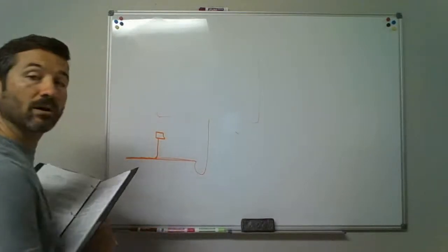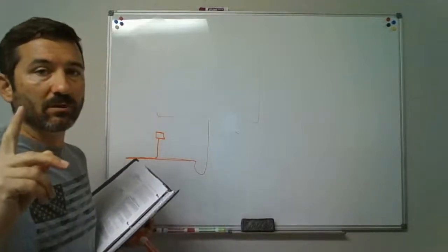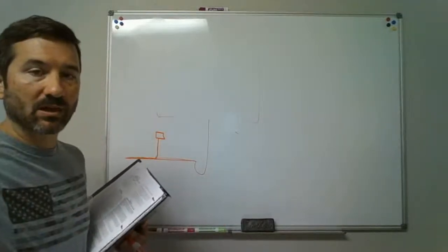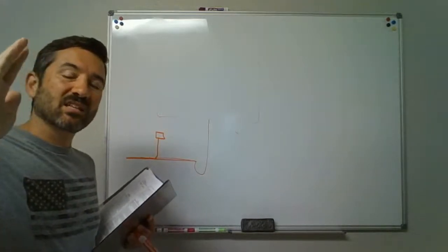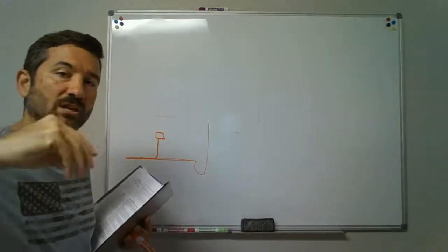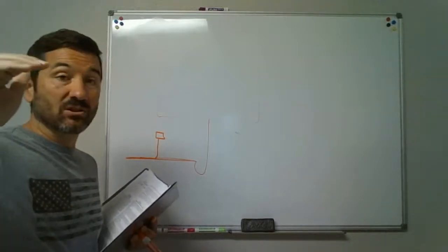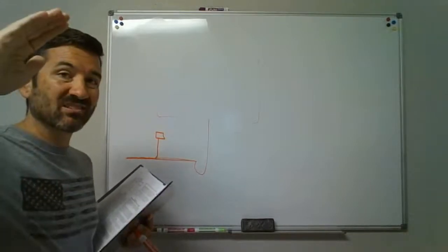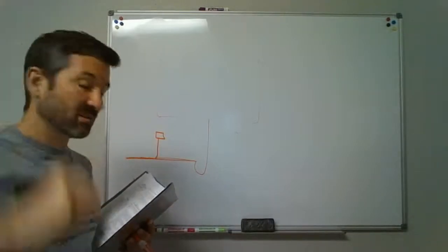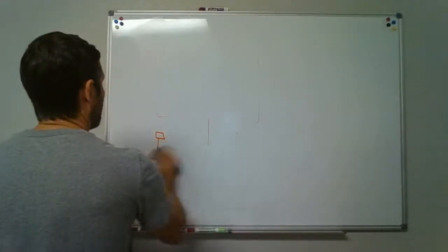If you do run one up into the attic, somebody says, "Hey, I'm adding this in, but I don't want you to put another hole through my roof," and you can't get it tied back to another vent. You can take it up into the attic as long as it's to an accessible location where you can get to it and change it out. About 6 inches above insulation material is what you're looking for. So if it's going above insulation in the attic, you've got to be at least 6 inches above the insulation to install that air admittance valve.